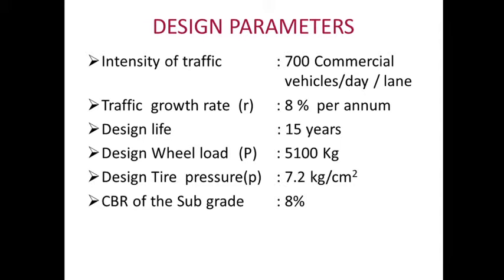The design wheel load is normally considered as 5,100 kg for heavy traffic. If it is medium traffic, wheel load is only 4,100 kg, whereas for light traffic, the wheel load is only 3,000 to 3,175 kg. Then another parameter is tire pressure.